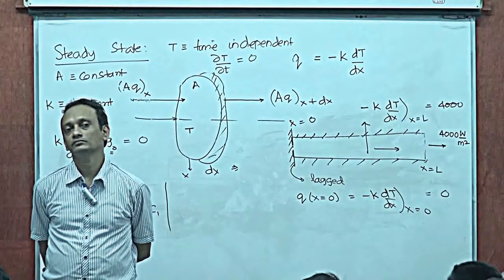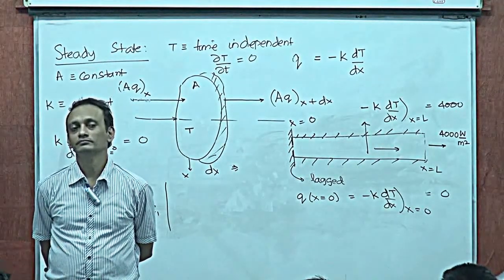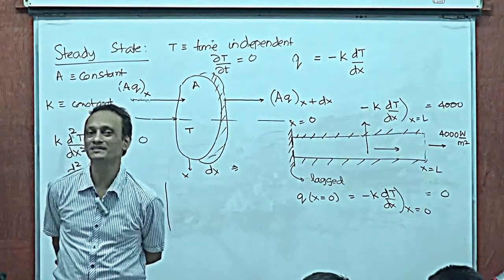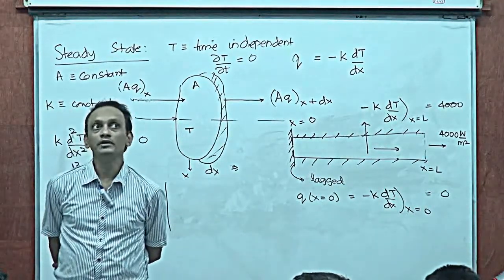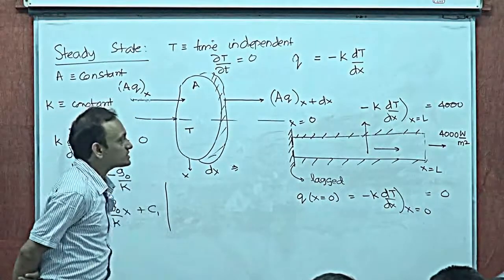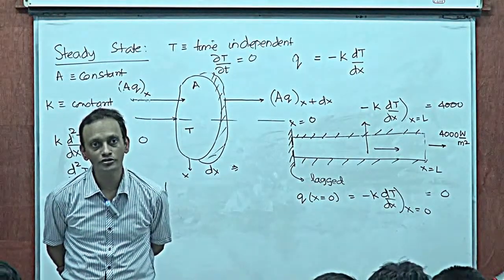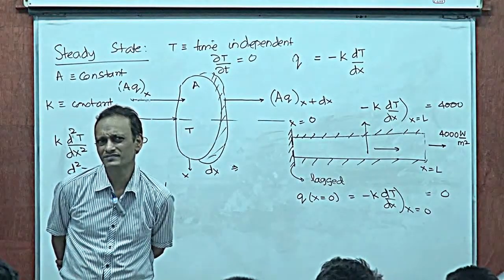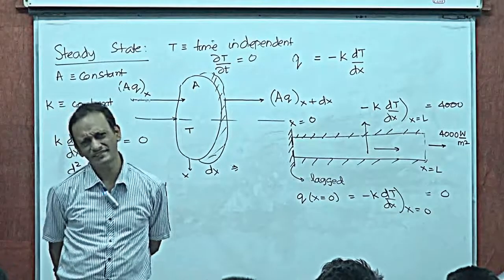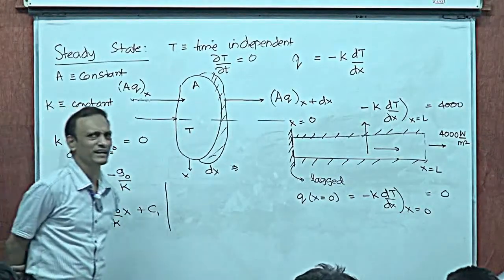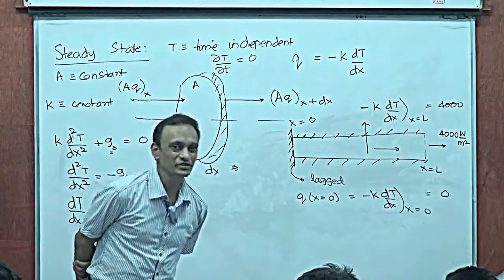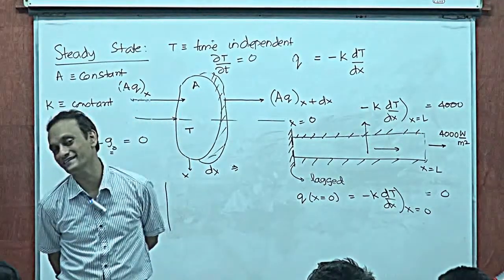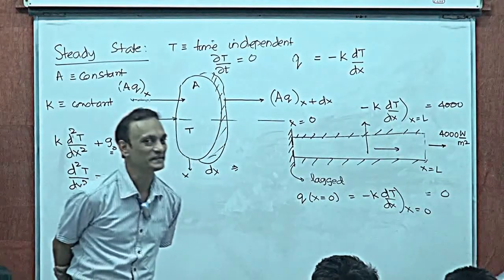Find out the equation for x, then with y. No, you can't superimpose that way. I mean, in that case, because it's not linear, isn't it? Do you realize that the expressions are not linear? You could superimpose if they were linear, but you can't superimpose stuff like that. You can't assume heat flowing in one direction and not in the other, then in the other direction and not in this one, and add them up. You can't do that, right?